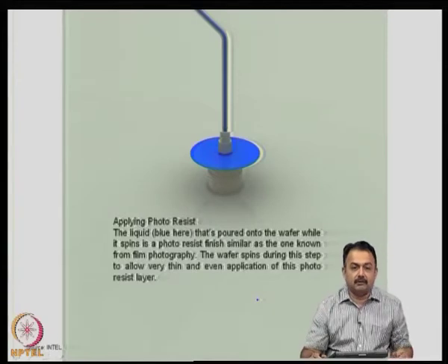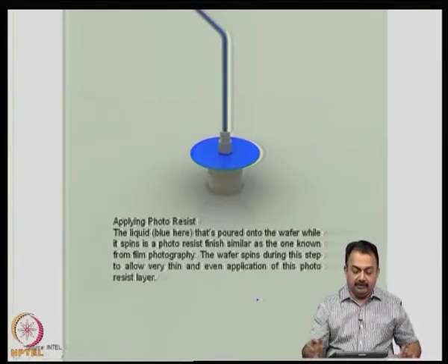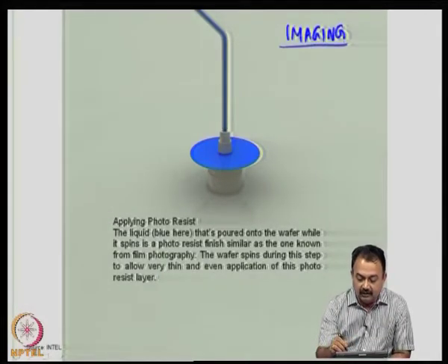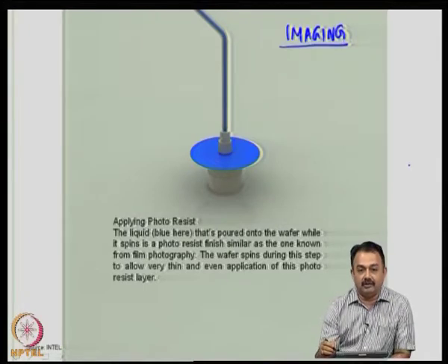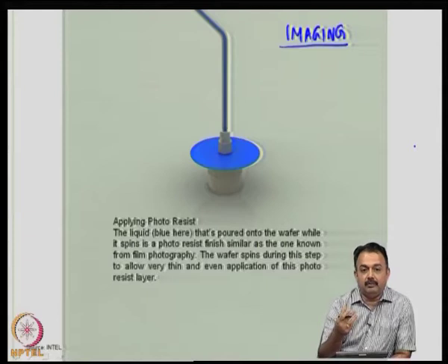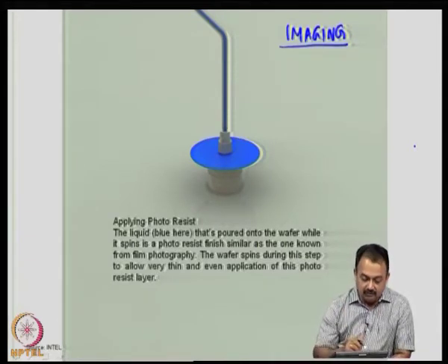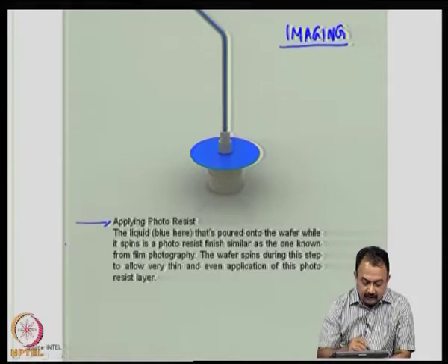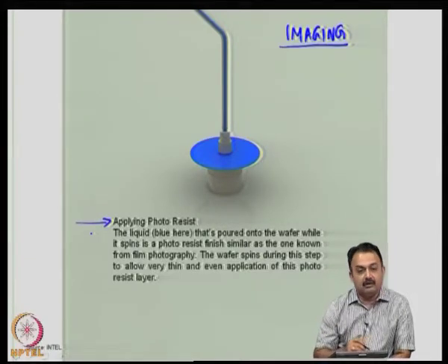Now, the next step is typically imaging, but for imaging your CAD design onto the surface of the wafer, you need to have a medium that will take up your design and realize it on the wafer. So, we go through what is known as a photoresist application process. Therefore, the next step is applying photoresist on the surface of the silicon wafer.